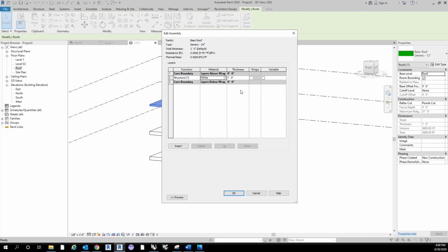And then instead of creating two layers of the same thing, let's just go in, click on the thickness, and type in 24 inches or 2 feet. That's the nice thing about Revit too. It's a little bit better than Rhino even.